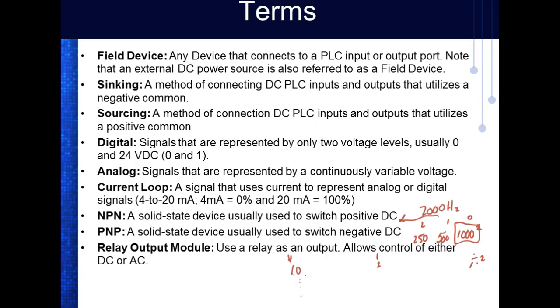But here we're in binary, so it goes in powers of 2: 2, 4, 8, 16, 32, 64, 128, and that would be how much it divides by. So you're not actually seeing the clock. All you're seeing is the least significant bit of the clock, which is a divide by 2. So if the clock's actually running at 2,000, the zero bit would only be running at 1,000. But you don't care about that because you're seeing 0, divide by 2, divide by 4, understand what I'm saying? So the higher you go up, the slower it runs.